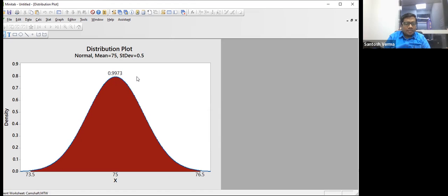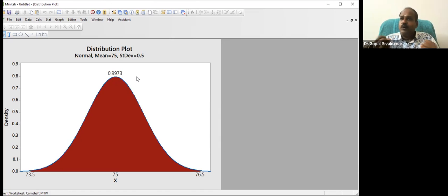99.73%. You almost know everything about what you are producing. Now, 99.73% of your offerings will definitely stay inside the control limit. Am I correct? Suppose the customer is okay up to 73.5 on the left side, 76.5 on the right side, what percentage of your products are now acceptable?